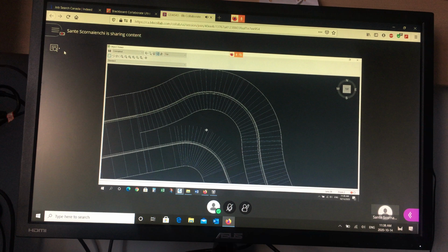Remember, the center line of the road is actually here. So these elevations here may not be representative. I want to design from my edge of asphalt all the way to my actual road center line. Right? So this gap, this hole here, doesn't make any sense. The elevations along this white line here are wrong. They're in the wrong spot, and they're probably vertically incorrect as well.